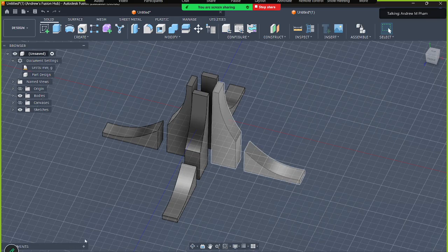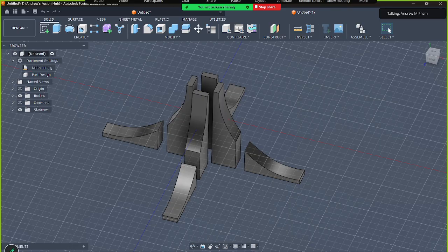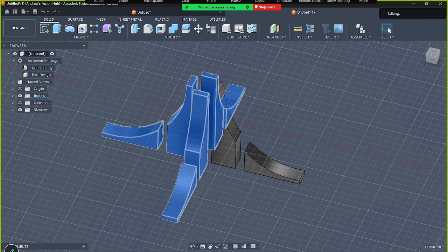So I'm going to roll it back just to eliminate any dependencies. Sometimes when I do it in a different order, where I pattern it and then I extrude things and modify things and then I try to move the pattern, some people accidentally select the wrong body, right? So if you were to not roll this back, you would want to edit the original one that we designed.